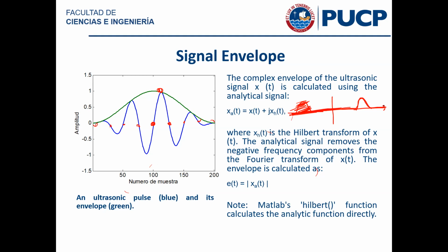And there are many, many ways that calculating the envelope can be done in practice. You could computationally calculate the Hilbert transform, of course, or you can do a demodulation. You could have this analytic signal calculated indirectly and then demodulate it back to baseband, centered around 0 hertz.